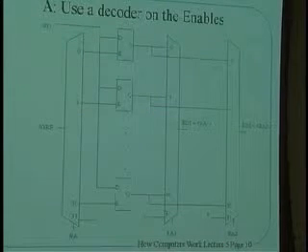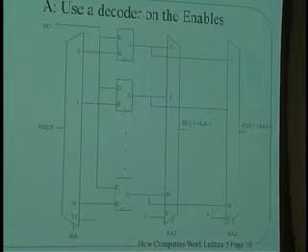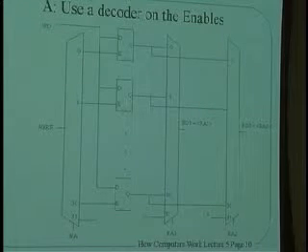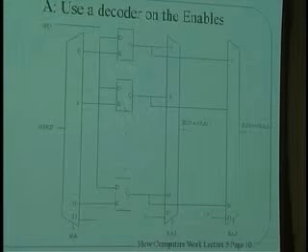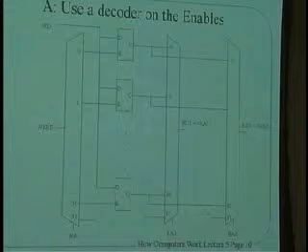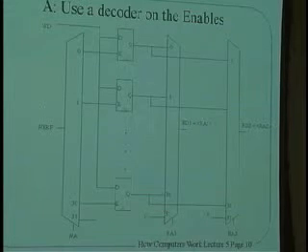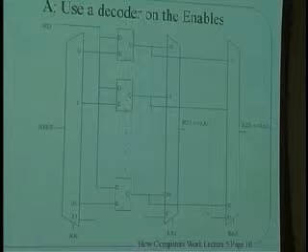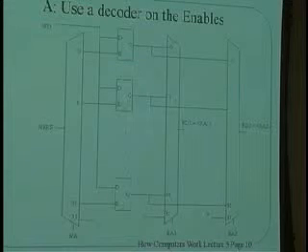So sometimes we want the machine to do something that does not involve writing to a register at all. And in that case, we make WRF equal to 0. What effect would that have on specifying an address, specifying data to be written to it? Then nothing happens here. Okay? But often that address is used for some other reason.